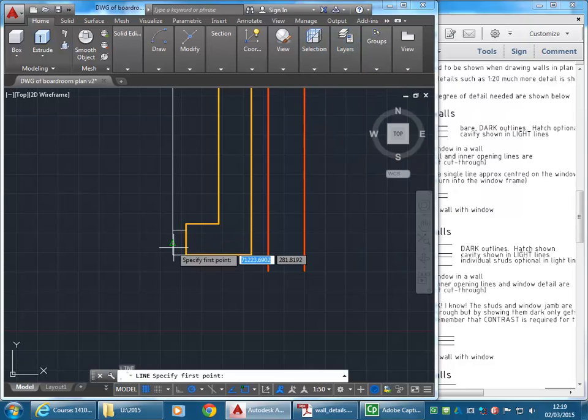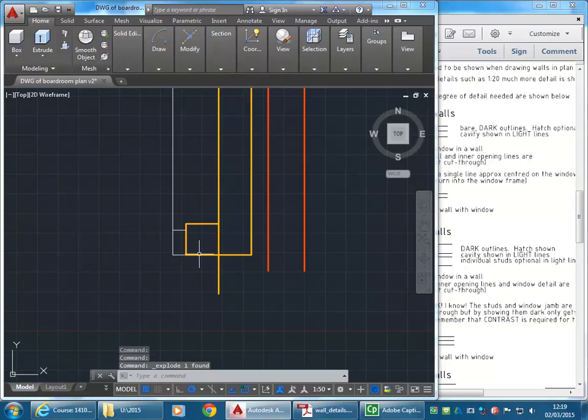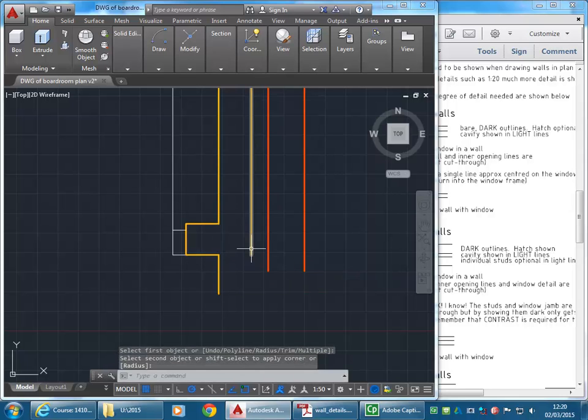Interior wall continuing below that, and then this, you can see why polylines after a while get in the way. Yeah, so you can just explode them. They'll save you a bit of time at first. Yeah. And so now it's easy to fillet that with the one below.